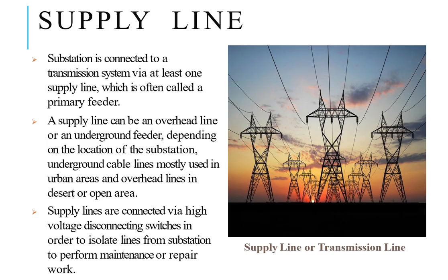Supply lines are lines to which the substation is connected. Yeah, for transmission purposes, a supply line can be an overhead line and an underground feeder depending on the location of the substation. Underground cables line mostly used in urban areas and overhead lines in desert or open area. Supply lines are connected via high voltage disconnecting switches in order to isolate lines from substation to perform maintenance or